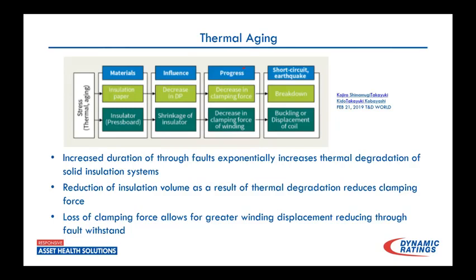And from testing in the field, I found that these slow operations generally are lubrication related, and they tend to worsen over time. So where you start out with something that's a few milliseconds and it goes to 2 cycles and maybe 10 cycles, but you have to remember, until we hit this 15 cycle point, we're not going to operate that bank breaker, and nobody's really aware that that's going on. But the transformer is still seeing all that. So now if we see a 3 cycle breaker, we could be exposing that transformer to 10, 12 times the duration of that fault current going through it than what it should be seeing if our protection was working correctly. So when you do that, you place a lot of thermal and mechanical stress on that transformer during that event, as with any fault.